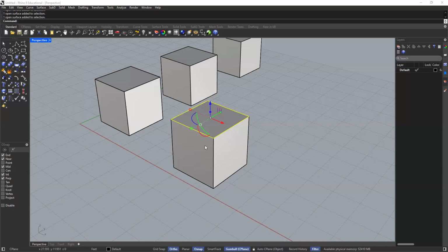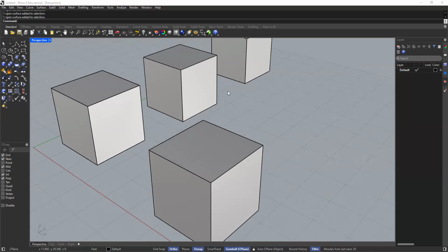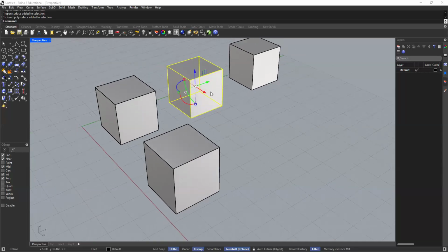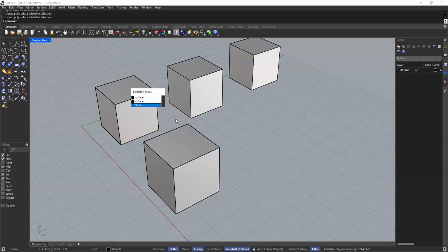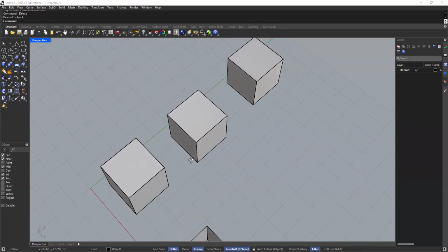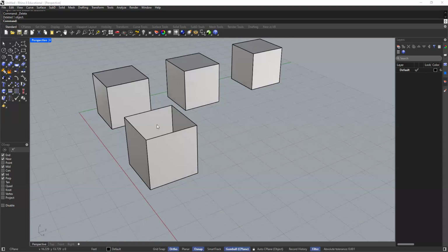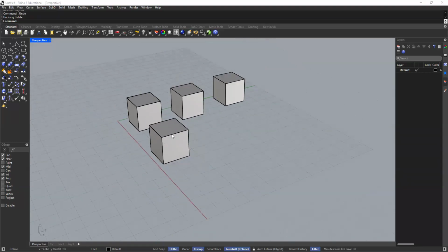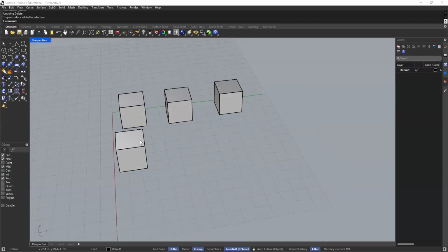Okay. It'll probably call these extrusions because we used the extrude curve command to create it. So the explode command has essentially turned this cube into this cube, because I can now take this and delete it, right? And now it's no longer a solid object. Well, what if I want that to be a solid object?